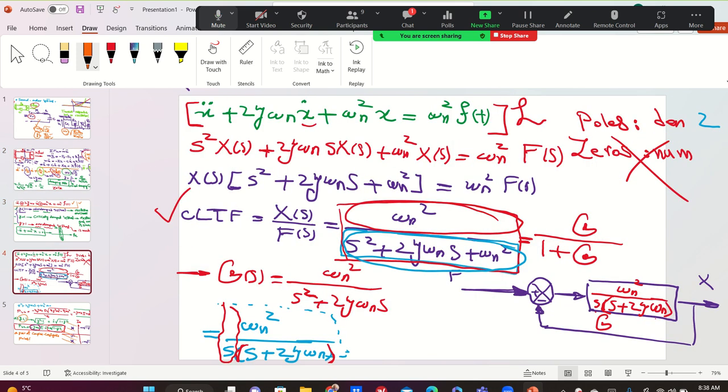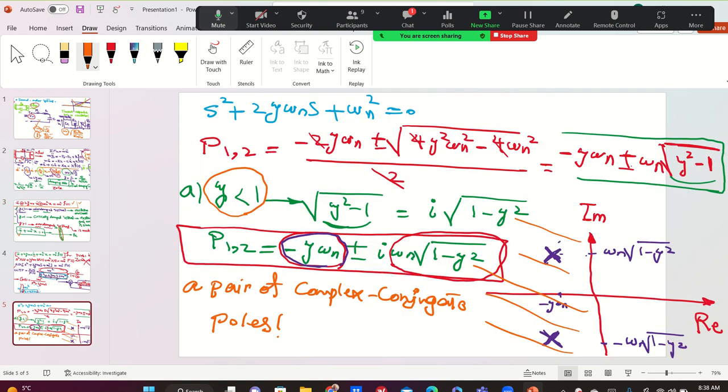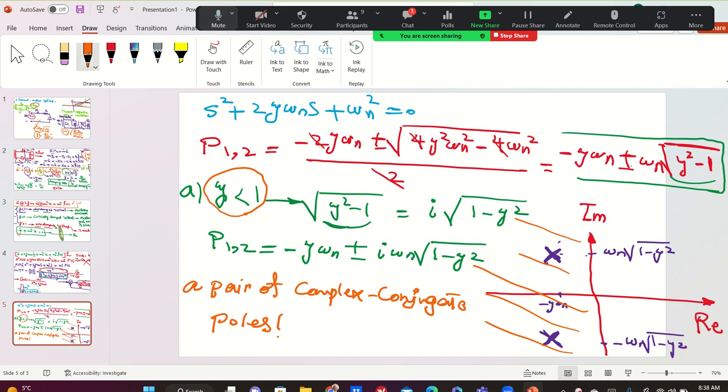Where I wrote it. Ha! Your system is marginally stable, man. With pure complex poles, your system is marginally stable, like a pendulum problem. Do you see any pure complex poles here? It has a real part. It has a real part. See?